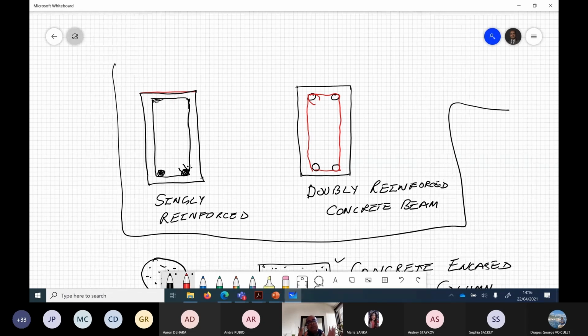It means that when the section dimensions are limited due to architectural reasons, you cannot increase the section size. If the applied moment is quite a lot, which the given section size cannot deal with using tension steel reinforcement, in that case you have two options. Either you can put compression bars, keeping the same sectional dimensions, or you can increase the size of the section if architectural requirements allow you to do that. So there are two options.